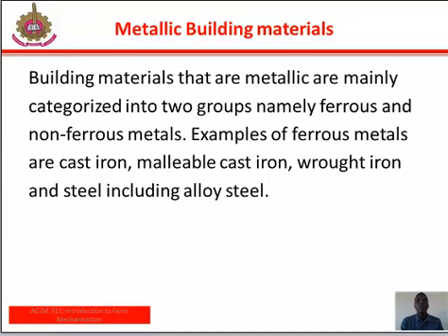Copper is useful in electrical installation in workshop and farm buildings. Brass is used for making pipes, instrument parts, and fittings, while bronze is an alloy of copper and tin, which is useful in bearing springs and pipe fittings. We also have aluminium or white metals, which is useful for coating chemical tanks and for light casting. It is also found useful in high-speed bearing. And lastly, we have zinc. Zinc is useful mostly in coating of iron sheets and die casting as a protection against corrosion.